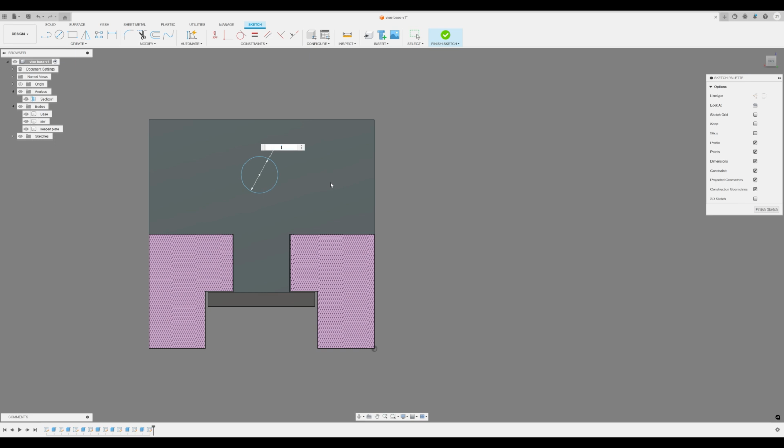So I'm going to go 0.4 or 400 thousandths, enter. And then I need this to be in the same plane on the z-axis as the previous hole, which fortunately I was keeping common size, so 0.5. And it will also be centered here, which will be 1 inch. So that is our first hole.